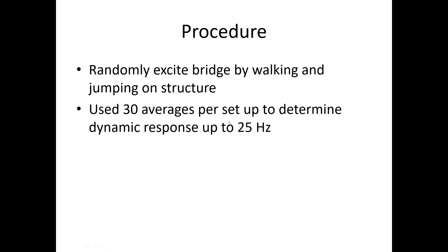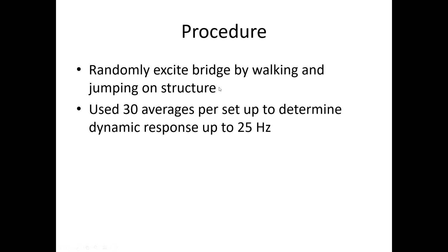Okay, and what we'll do is be measuring the response of the bridge just to operational forces, or basically a few people just walking around. Maybe we can have some jumping and things as well if we want to simulate more of an impulse. But just normal walking or jogging on the bridge should be enough to get enough motion that we can measure and see what's happening. We'll measure up to at least 25 hertz, though again, most of the modes we're interested in are down below about 5 or 10 hertz. And that's basically the plan.